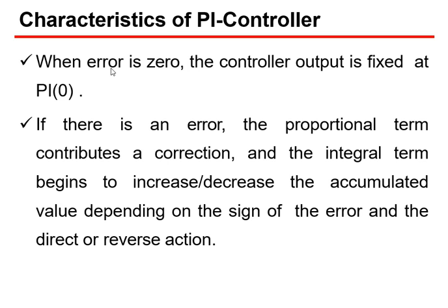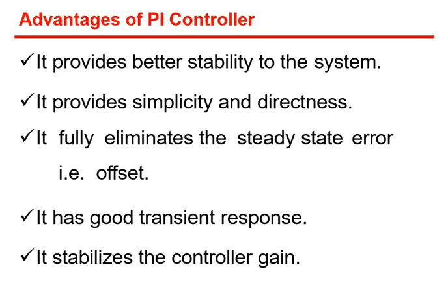So when error is 0, that PI is 0, that we have seen, and the proportional term contributes correction, and the integral will increase or decrease based upon the accumulated value. Okay, so these are some characteristics of a PI controller.